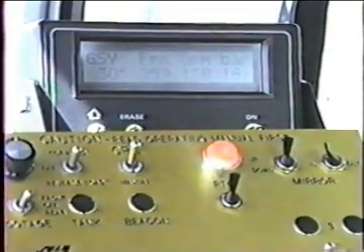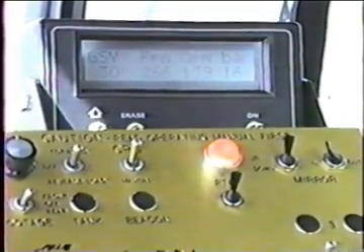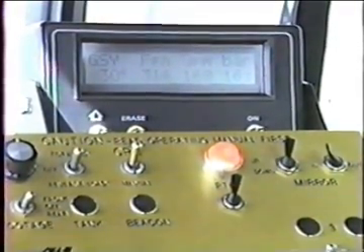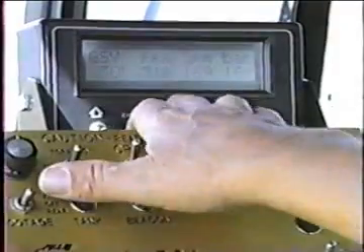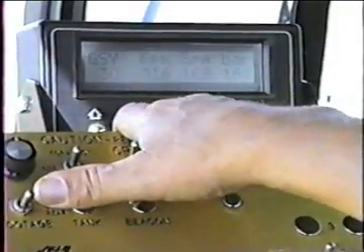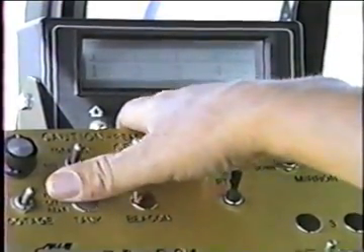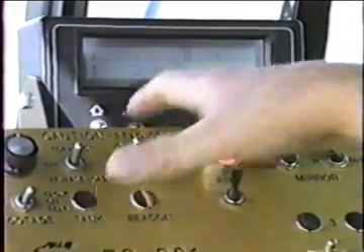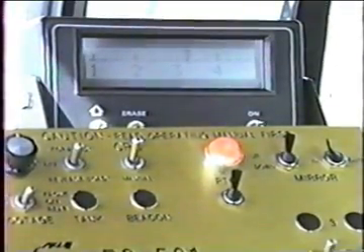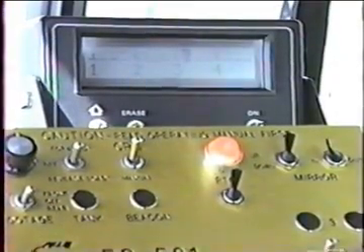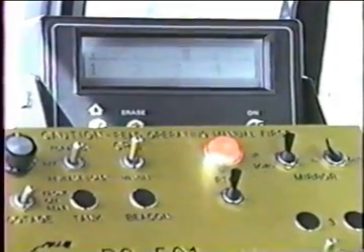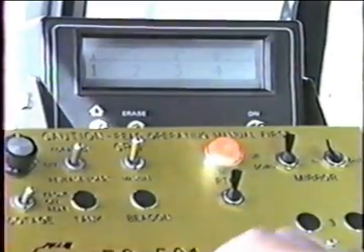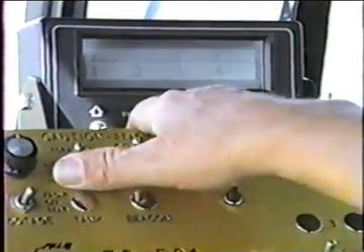If we speed the truck up, as I speed up, now you see 3. That's telling us that at this speed, we should have number 3 nozzles. That's the same as we see over in this mode, on the nozzle size graph. That tells us exactly where we should be. If we want to be at the ideal speed for number 3 nozzles, we should slow down very slightly. Now we've slowed the truck down very slightly.